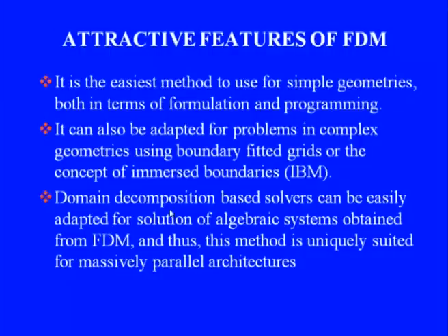The other advantage which we have is that we can use domain decomposition based solvers if we are dealing with very large scale numerical simulation, which we have to routinely do for the solution of industrial problems, specifically the problems which involve turbulent flow. Now the whole problem cannot be solved on a workstation or a single computer, and we have got to use massively parallel computers for numerical simulation. And for these parallel simulations, we normally use what we call a domain decomposition based approach, and finite difference method is one of the easiest to adapt to this domain decomposition approach. Now let us have a